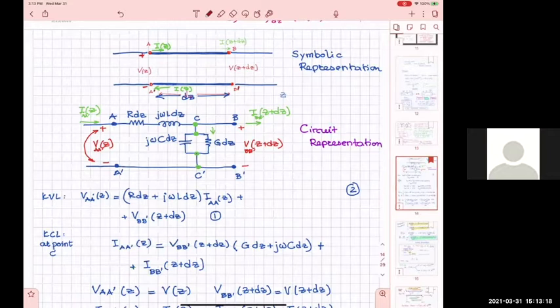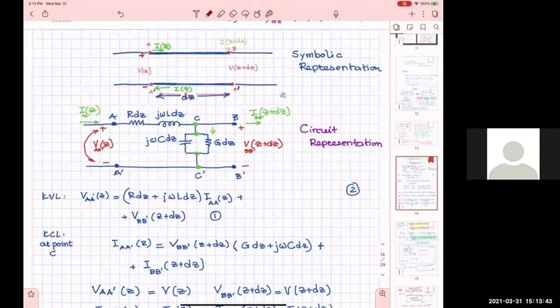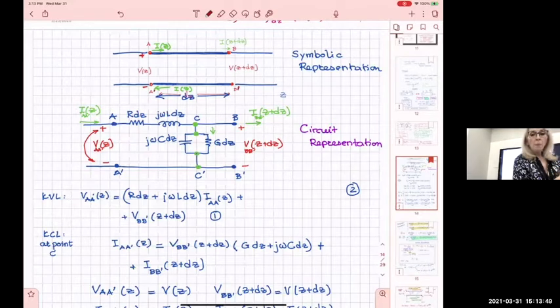Why do you need a separate resistance and a separate conductance? Because the resistance comes from losses in the wire, and the conductance comes from losses in the material that separates the two conductors. So in the microstrip, it is the dielectric substrate. Imperfect dielectrics have losses. And those are represented as conductance? Exactly. That makes sense. The units of G are 1/ohm per unit length, and R is ohm per unit length.